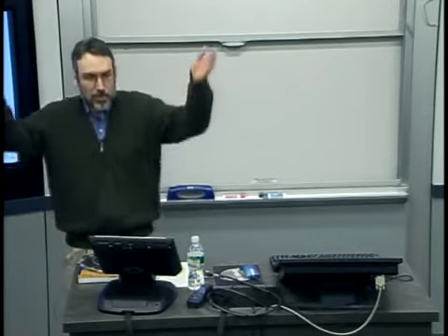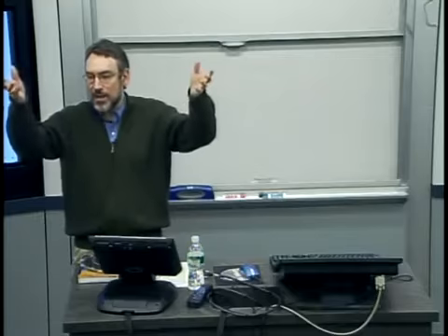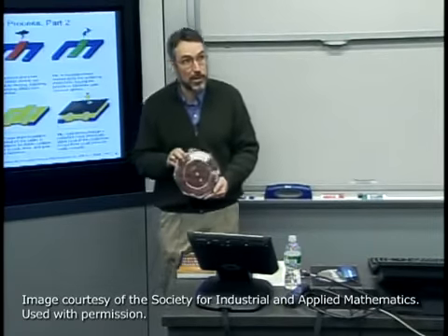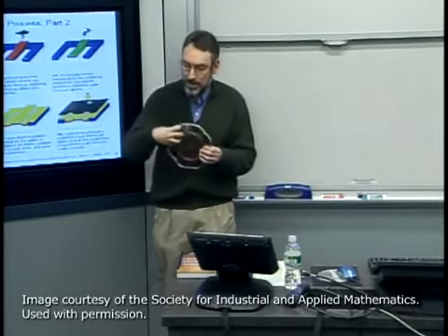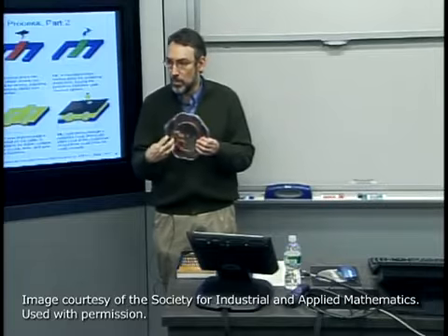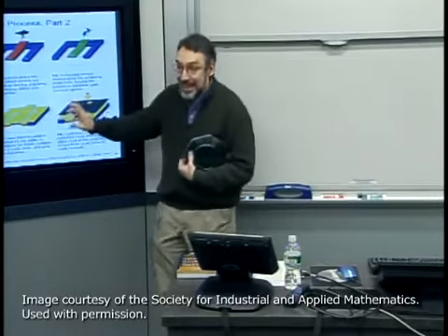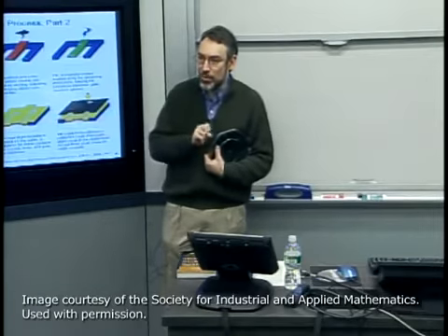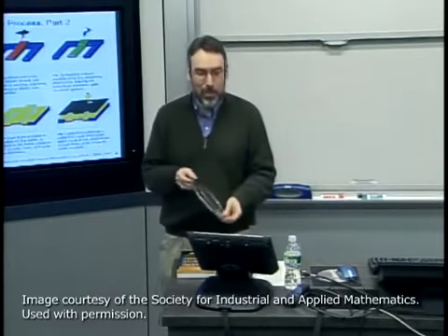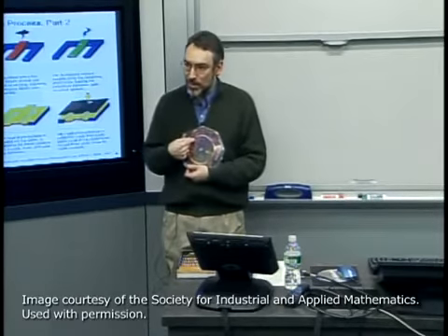One step was photolithographic reduction from, say, a 10-to-1 or a 5-to-1 glass plate down to a smaller chip or smaller wafer. The second was chip-to-chip stepping. So in fact, the photolithography equipment is typically called now a stepper because it's imaging one field, maybe one chip. There may be more than one chip in each field, but I'm stepping through in order to get the control and be able to achieve the alignment on one chip at a time. And in the most modern equipment, in fact, they don't even image the whole chip at one time.